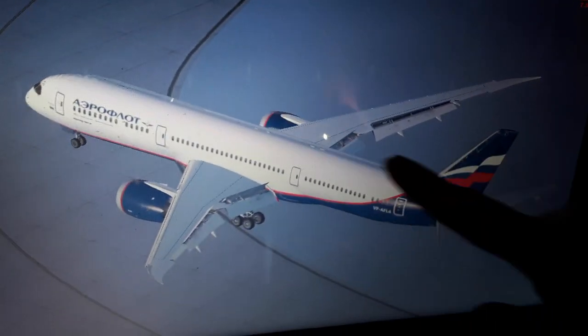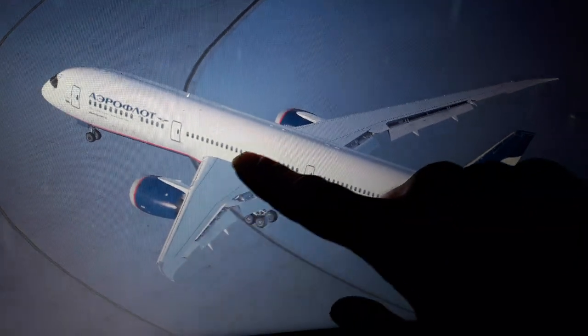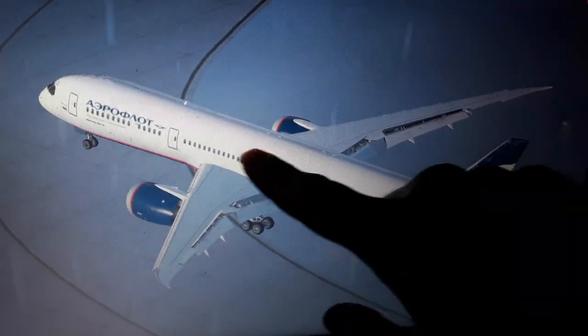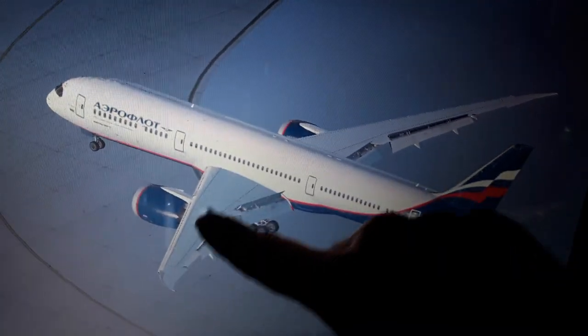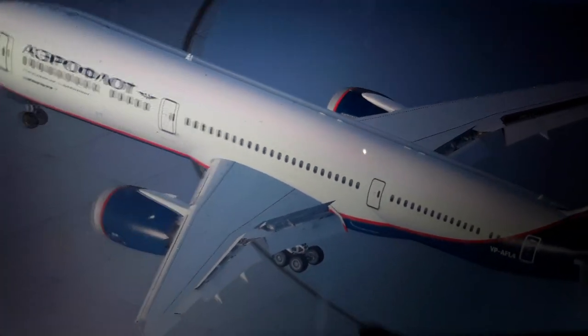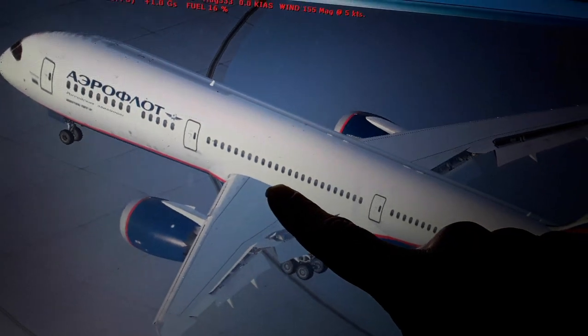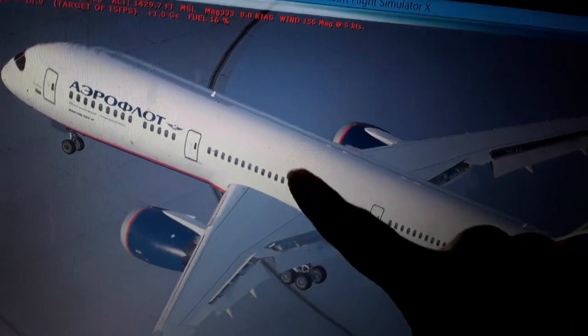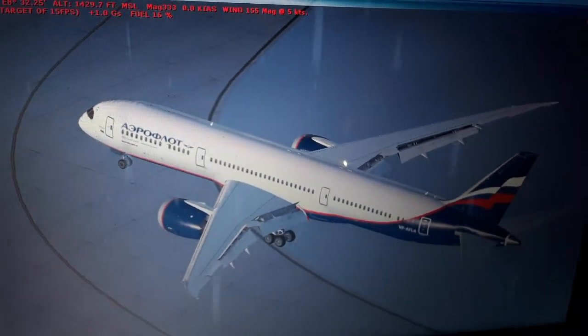We have the thrust from the engines. The mean aerodynamic chord position is about 33% of the MAC, where the maximum aerodynamic lift occurs in the wings, approximately here, 23% of the mean aerodynamic chord, where the stall also begins in flight, where we calculate the center of gravity for an airliner aircraft.